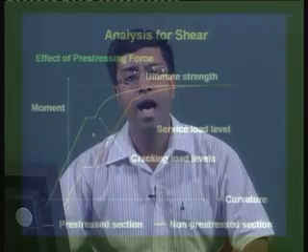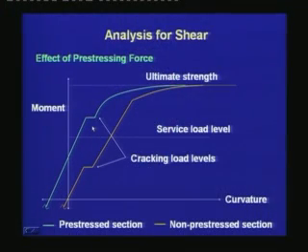This type of sections has a cracking load which is higher than the service load. After cracking, we observe the nonlinearity in the behavior and the strength tapers off to the ultimate strength. These two curves have been drawn for a reinforced concrete and a prestressed concrete section, which have equivalent flexural strength.